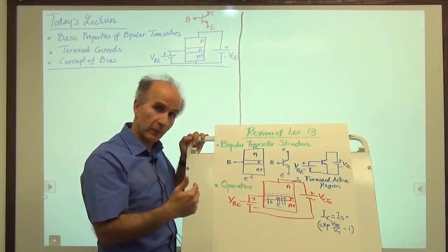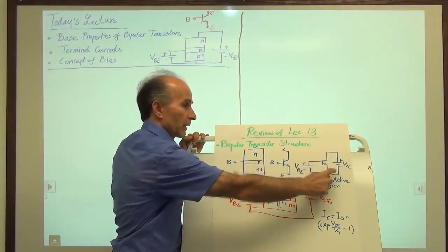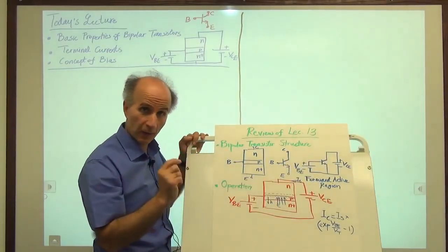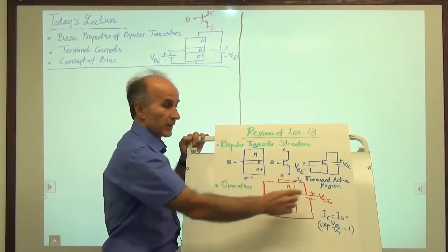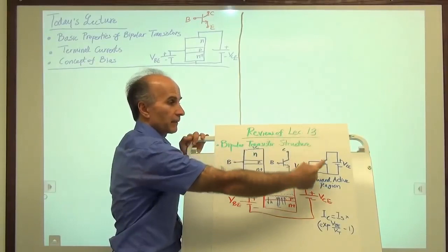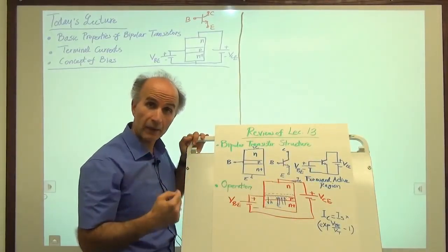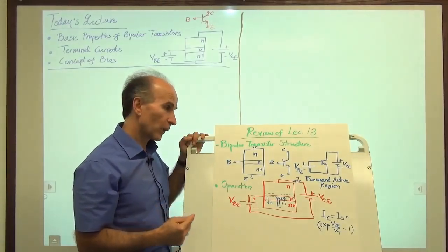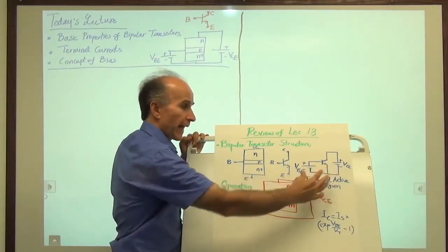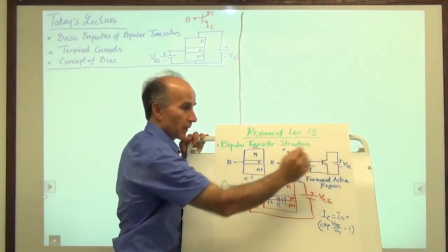And as we saw last time, we prefer to place a voltage source between the collector and the emitter, not between the collector and the base, to create that condition. We see that if this voltage is high enough, then the collector will be higher than the base and that junction will be reverse biased. Okay, we call this the forward active region. If we have forward bias here, reverse bias here.